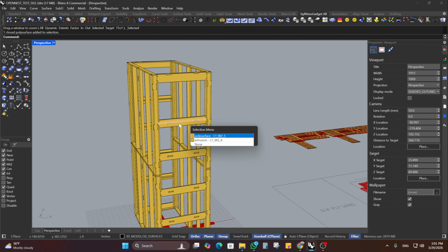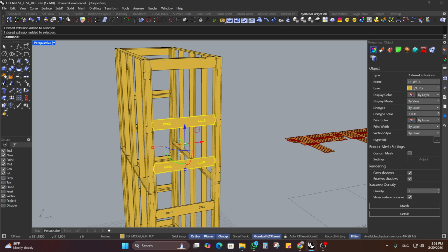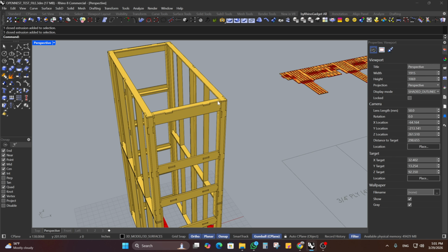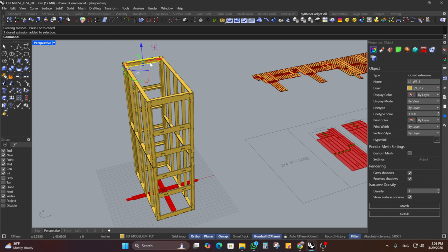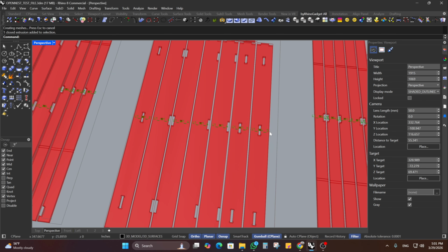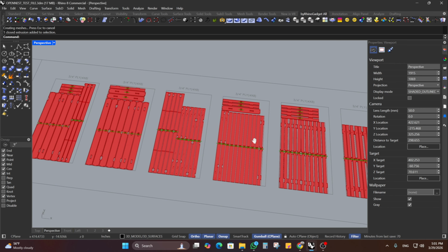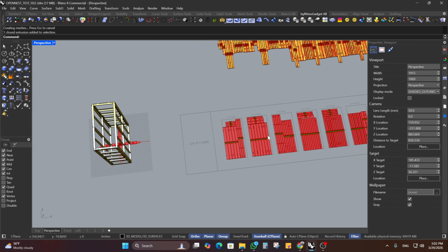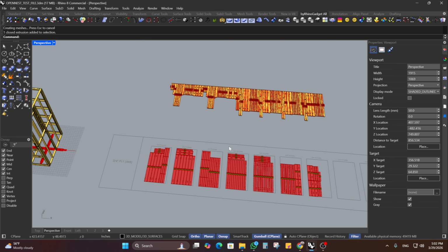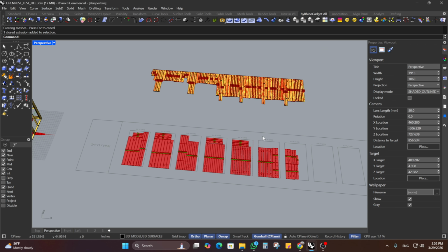And if there's duplicate parts, I've just given it the same name. The whole point of this type of nesting is to take the names from the objects and then transfer them onto the nested parts, and then be able to engrave them or laser etch them or whatever. And that's how you keep your labeling system consistent.